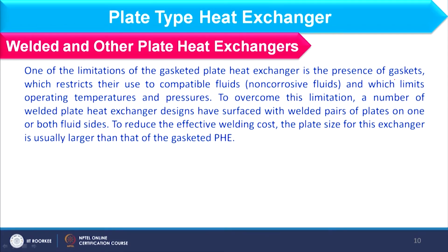First of all, tell me what is the limitation of the gasketed plate heat exchanger. The material of the gasket is usually rubber type, fine. So we cannot handle very high temperature or very high pressure fluid in such heat exchangers when I am using the gasket, because the gasket will tear and the fluid may come out.